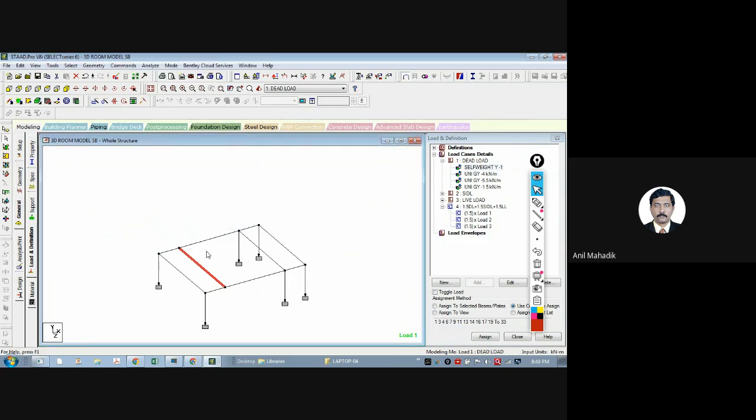And for those bending moments, I will design for 750 size. So that is the iterative process. So don't keep the model sizes different and drawing sizes different. Otherwise, the bending moment distribution will be different. It is always expected that the sizes of the model, sizes of the design and drawings should be the same, and on site also definitely.